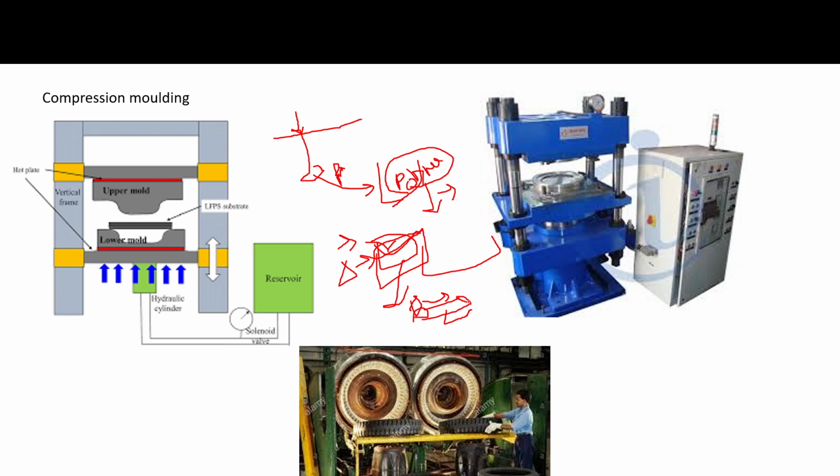But thermosetting polymers are not reprocessable, because in thermosetting polymers the chains are cross-linked to each other. Cross-links mean that when we heat it, the polymer chains cannot pass each other, so they behave like a solid material.